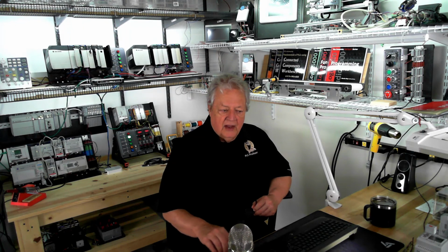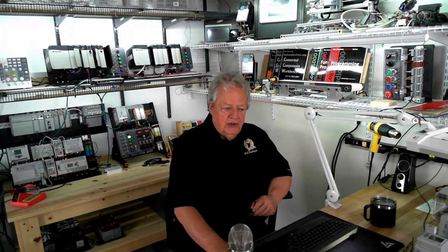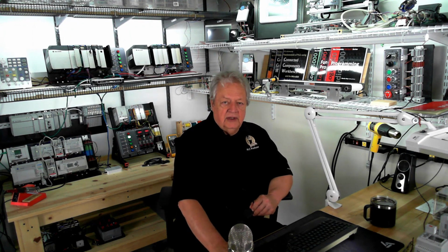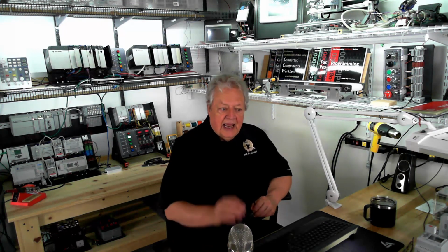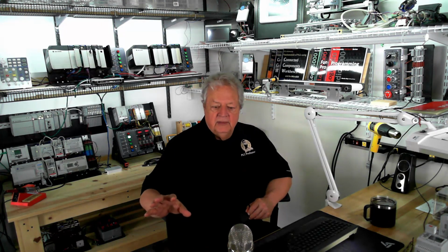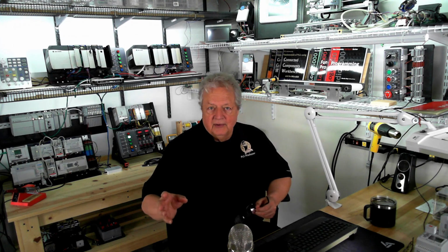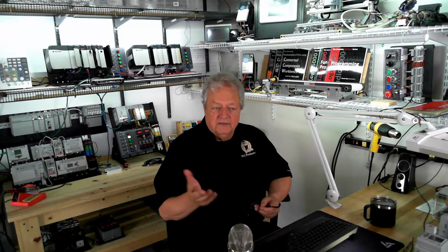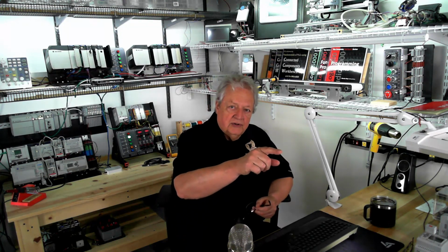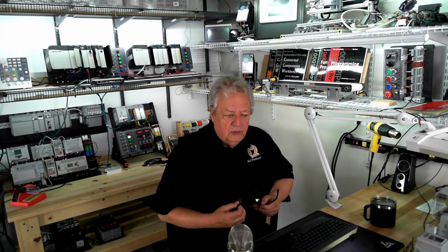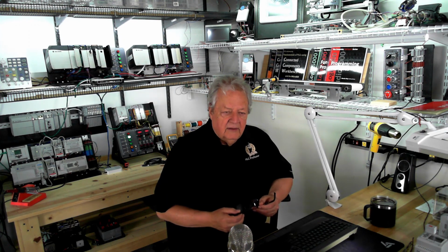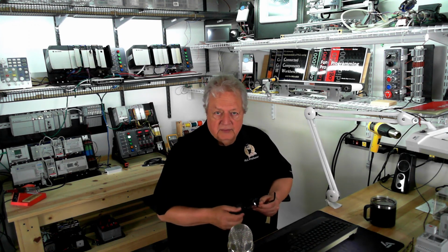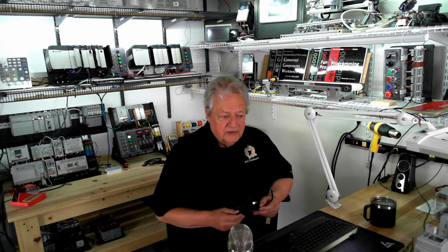If you go on without doing so, you're never going to use this logic specifically in a practical application with an actual real conveyor or system, because with a real system, you've got a real push button, right? You push it, the bit goes on, you release it, the bit goes off, or vice versa. The bit's on, you push it, it goes off, and then it comes back on. So you wouldn't use this kind of logic for push buttons because you have real push buttons, but you will see it in other code when you get into other people's programs at work.